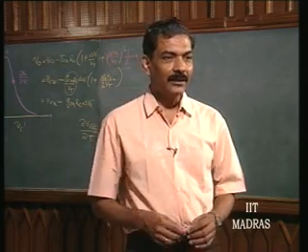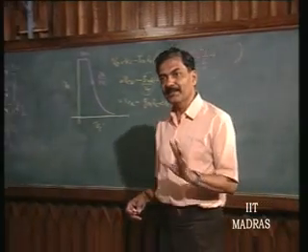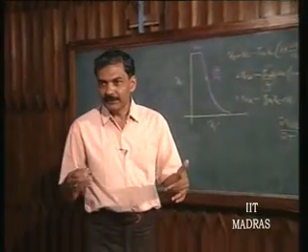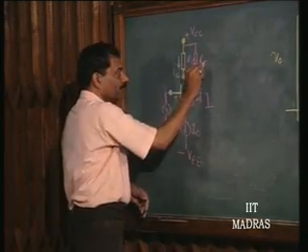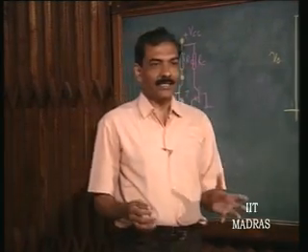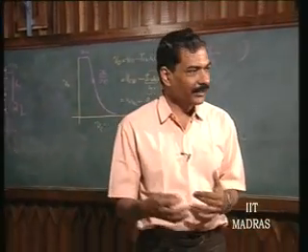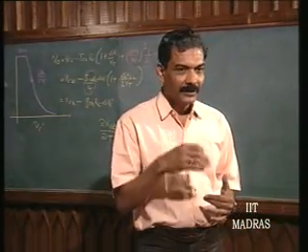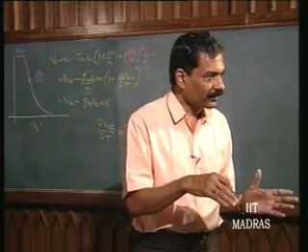Now, what is this? This is nothing but the differential amplifier. I mean, this is one way of presenting the differential amplifier. It is not how this has developed. Is this clear? This is one way of presenting the differential amplifier as something that has originated out of necessity of getting rid of the disadvantages of the discrete common emitter amplifier when it is being adopted for IC version.